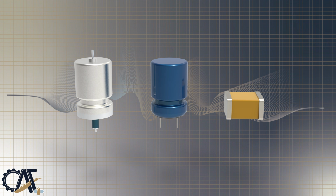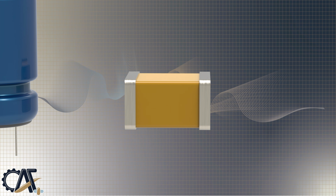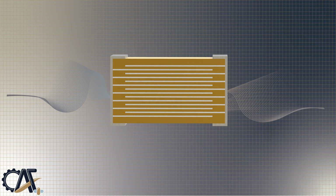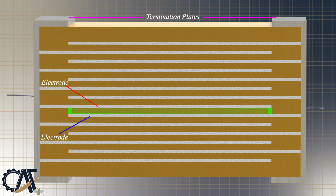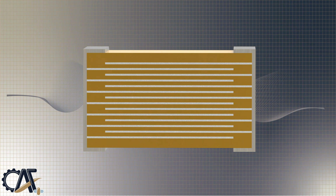These multi-layer ceramic SMD capacitors consist of a rectangular block of ceramic dielectric in which several interleaved precious metal electrodes are contained. This structure gives rise to a high capacitance per unit volume. The inner electrodes are connected to the two terminations, where one side of the metal layers will act as the cathode terminal, and the opposite side as the anode terminal. Also, the size and the number of layers determine its capacitance. They are small, leadless, relatively cheap to manufacture, and have a very low spurious inductance. Thus, they are widely used in high-volume production printed circuit boards.